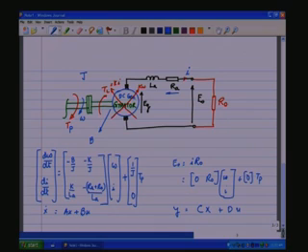So, this forms the state equation representation of the DC generator, or the mathematical representation of the DC generator in state equation form, and this is the dynamic model. As we said, in the steady state model, LA will vanish and we just have the resistive drop which comes into the picture.